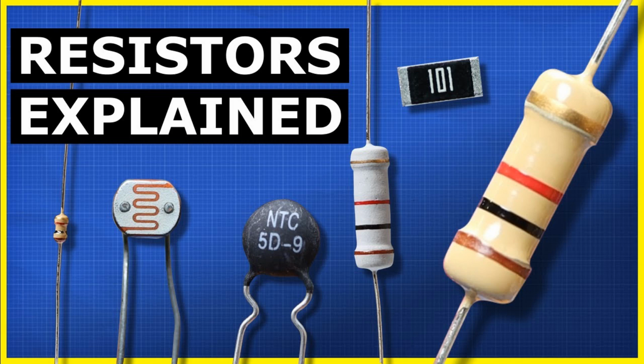Precision resistor types. Precision resistors, such as metal film, metal foil, and thin film resistors, are often chosen for applications that demand high stability. These resistors are manufactured with tight tolerances and low TCR values to ensure stable performance. Calibration and testing. In some applications, resistors are periodically calibrated or tested to ensure their continued stability and accuracy. This is common in industries where precision and reliability are critical, such as aerospace and metrology.